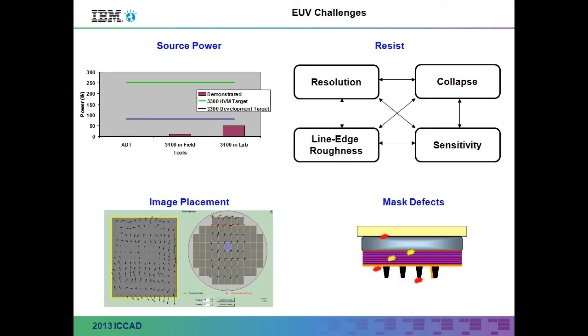Resist optimization is very difficult to do when you don't actually have enough light to do these experiments efficiently. And there's a lot of balancing, right? If you make the resist too sensitive, then you get a lot of shot noise, you get very raggedy looking features, you're printing very small images so they have a tendency to fall over. So all of that co-optimization is still ongoing.